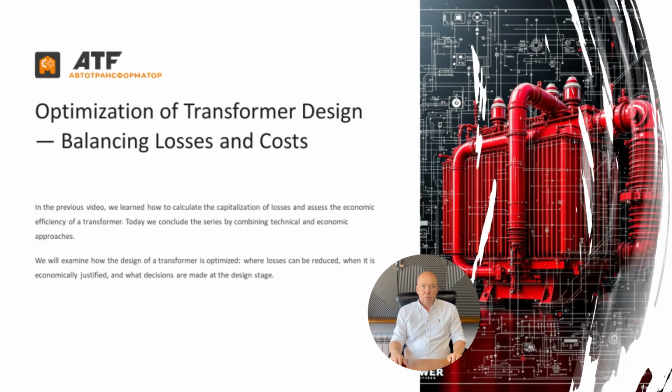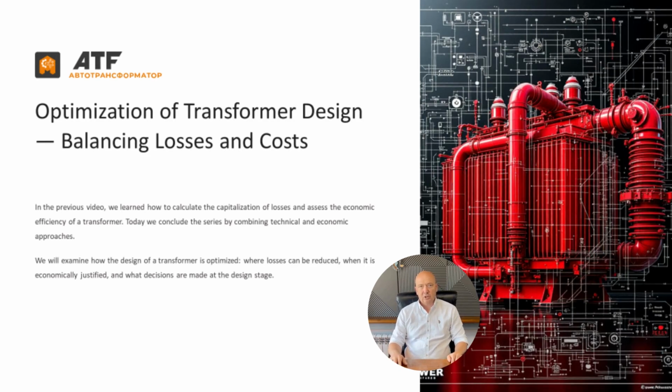In the previous video, we learned how to calculate the capitalization of losses and evaluate the economic performance of a transformer. Today, we conclude the series by combining technical and economic logic. We'll explore how transformer design is optimized, where losses can be reduced when it's worth the cost, and which decisions engineers make during the design phase.